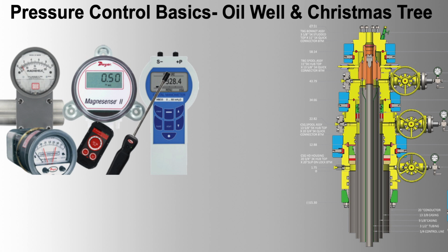Example issue 4. Corrosion of downhole instruments. Problem: corrosion of pressure sensors, leading to inaccurate readings and potential failure. Solution: replace sensors with models made from high-grade corrosion-resistant materials like Inconel or Hastelloy. Implement chemical treatment programs to reduce corrosive elements in the well.